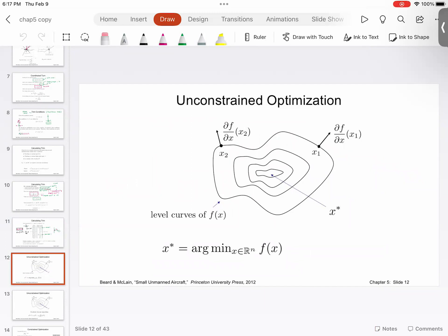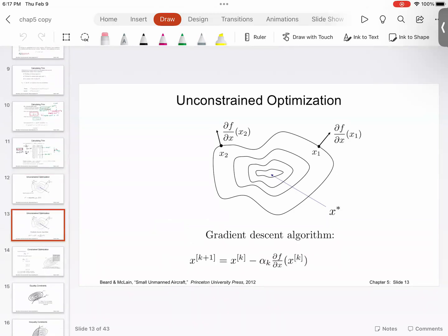So then the way we solve the trimming problem is by means of constrained optimization. In the last class, I gave you a basic idea of what optimization is. At the core, optimization is taking the first derivative and equating it to 0. And depending upon if you constrain the value of states, or if you add some additional condition on the derivative or the states, that is constrained optimization. If there is no boundary, no constraint, then that is unconstrained optimization.